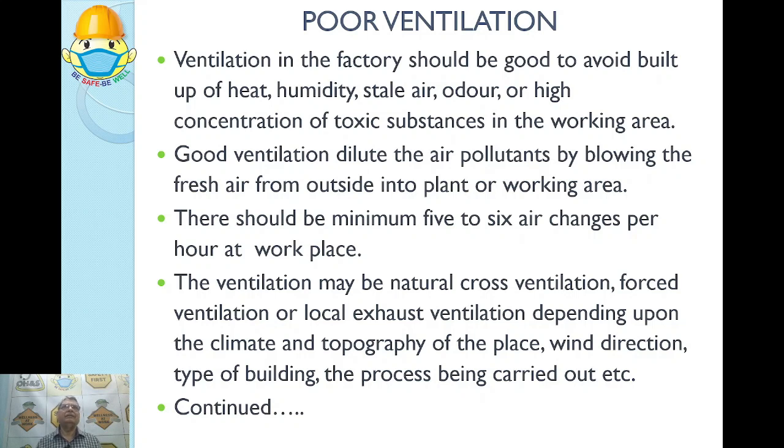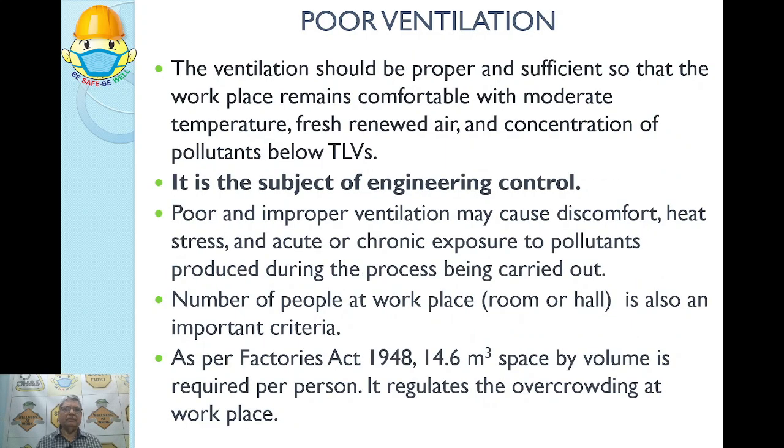And climate, if it is very hot climate, you need more air exchanges. If the climate is cold, probably the requirement of the air changes will be less. So it depends on the climate, topography of the place, wind direction, as I said, type of the building, the process being carried out, and so on. And ultimately, if that is not enough, you may have the air conditioning. So air conditioning will take care of all the ventilation problem.